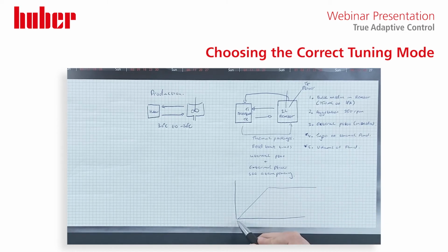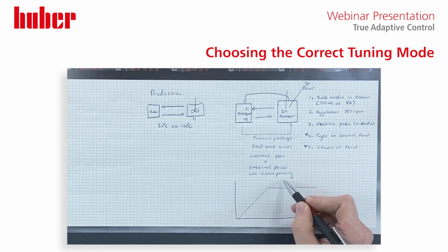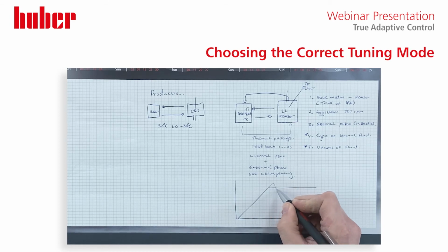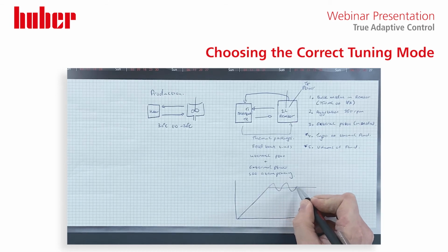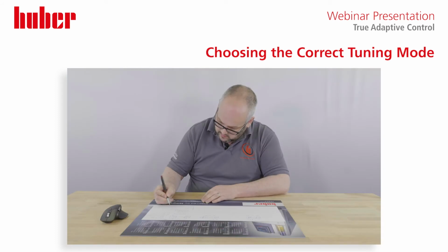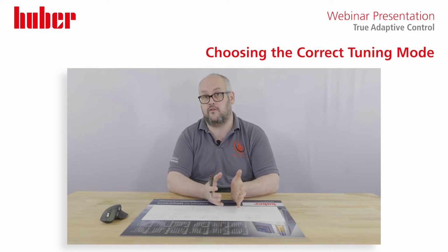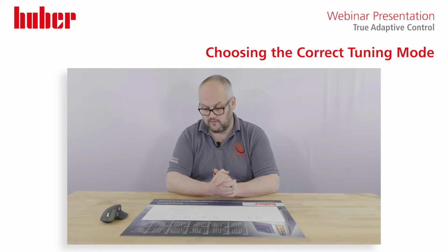And it's looking at the time it takes to heat up to get to roughly the set point. But it will also look at, am I getting an overshoot or an undershoot? Sometimes the machine will tell you your results are nonsense. This does not make sense.